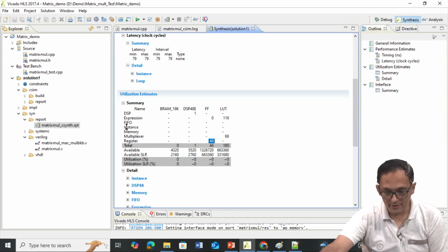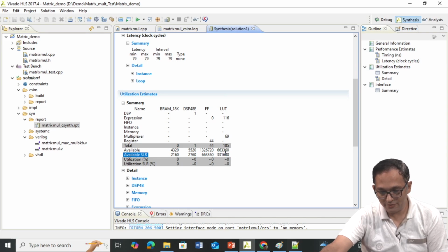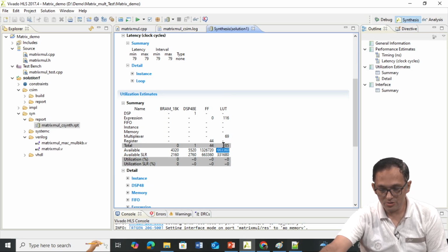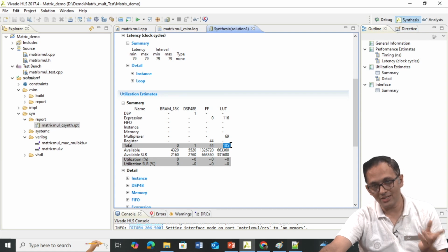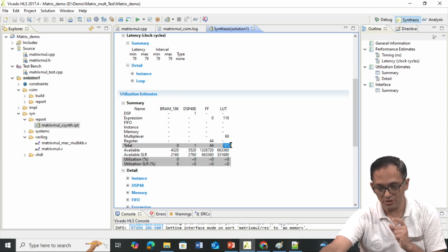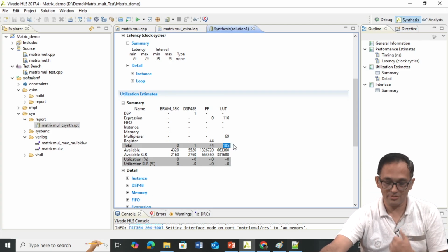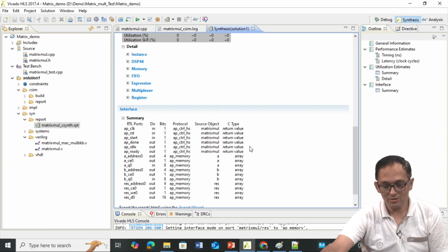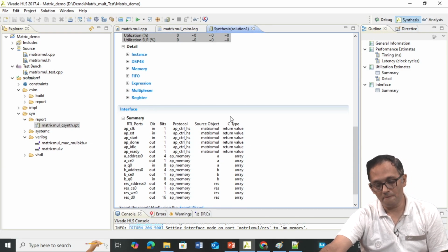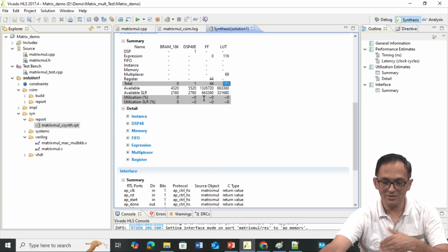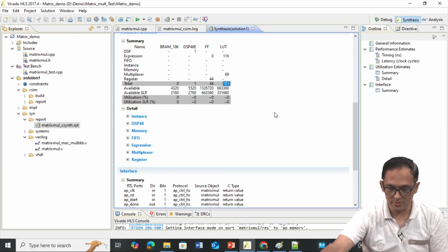And then you also have the LUTs, which are basically, you have 6 lakh in the board you have selected. It only uses a total of 185 for this addition, multiplexing and all those things, right. So it effectively uses 1 DSP, 44 flip-flops and 185 LUTs. This is a baseline implementation, okay. So this is how we can see the kind of resource utilization, okay. It is much lower than the available, so you should not be worried, okay.